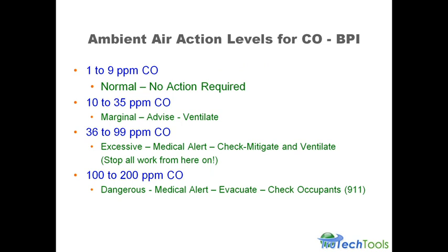I've seen CO levels in furnace stacks over 19,000 parts per million. If that was venting in the space, you may not have a chance to even react to it before you get overcome by CO. 100 to 200 parts per million in ambient air is extremely dangerous. You should call 911. You should get the occupants checked, because they probably are going to have some CO poisoning.